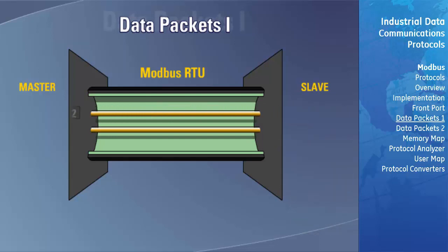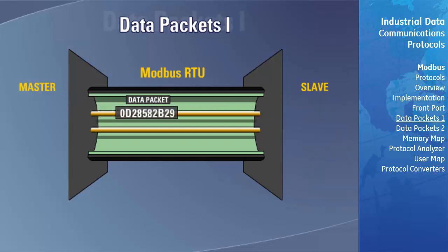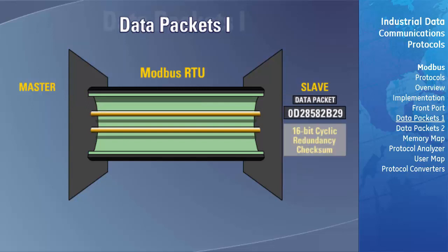During transmission of the second data packet, an error occurs, and there is a silent interval created of 2 character times. When the slave receives this silent interval, it will discard the corrupted second data packet and not send any acknowledge signal. The master will then resend the second data packet because it received no response. The slave will then error check this data packet and send back an acknowledge signal. The third and final data packet is then transmitted error-free, and the slave sends back an acknowledge signal. This concludes the successful transmission of the message from the master to the slave.